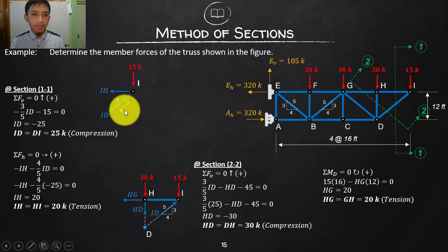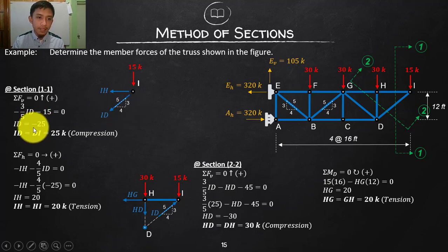By the way, in here, I solved this to be negative in this preliminary assumption. So again, as I've said, if you change the direction based on the sign, if you corrected this one, and then you will be using the figure again for the next solution, you will be carrying the positive since you already corrected. But if you did not correct it here, this direction, just like what I'm doing right now, okay, I did not change this one. I will just be following the preliminary assumption that that is tension. But of course, I already know that that is compression. Therefore, I will still follow the direction, but this time I will be carrying the sign, which is a negative. Okay, so that should be clear by now.